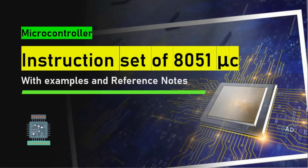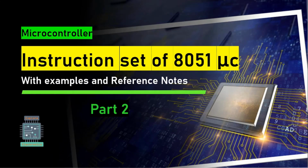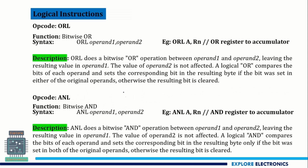In this video, let's see the instructions of 8051 microcontroller and let us look into each and every instruction with examples. Then we have logical instructions. Logical instructions in the sense logical AND, logical OR, logical XOR, these kinds of operations. ORL corresponds to OR operation. It is a bitwise operation.